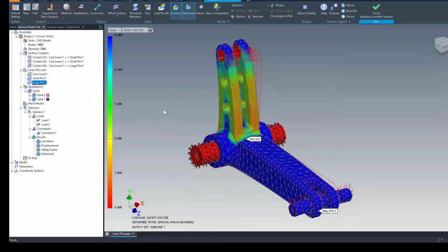So that was the basics of start to finish for a NASTRAN simulation, and it's more or less a typical simulation. Many people are running a linear static simulation as a start to maybe running a nonlinear static or a buckling simulation next. This is kind of the groundwork to make sure you get all of your constraints and your loading right and make sure it's stressing the way that you think it's going to be stressing.